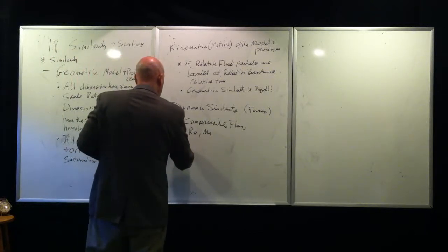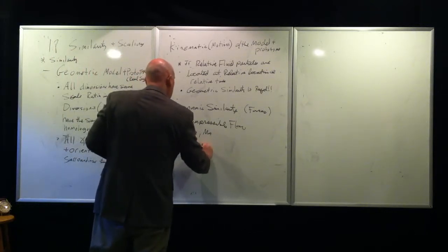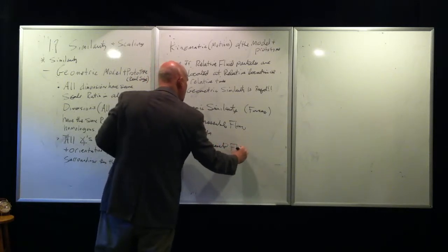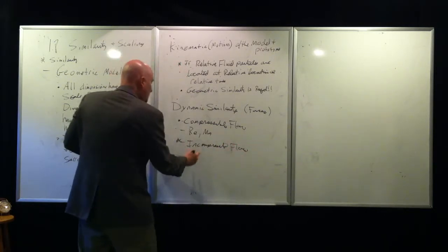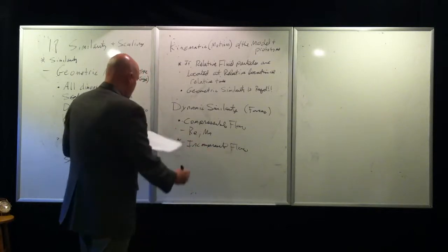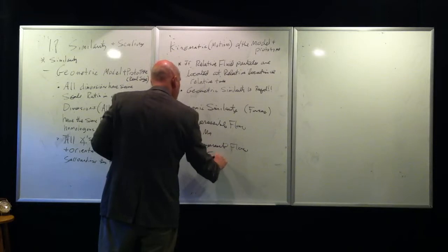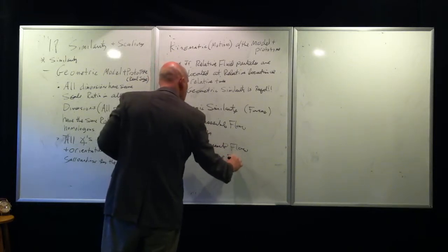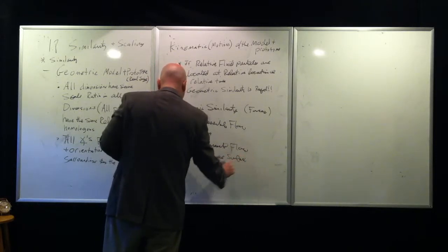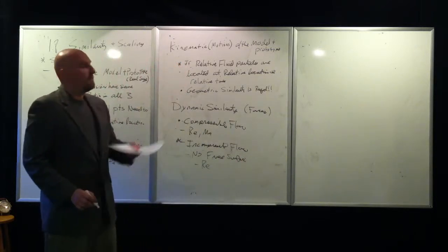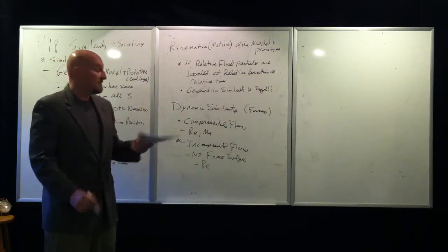If you have incompressible flow, and let's say no free surface, you just have to have the Reynolds numbers between the model and the prototype be the same.